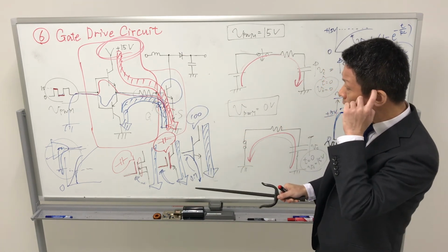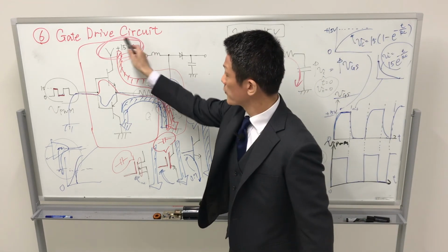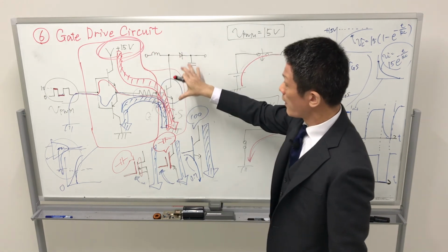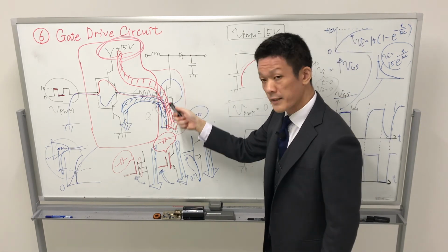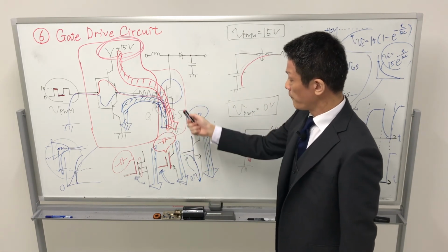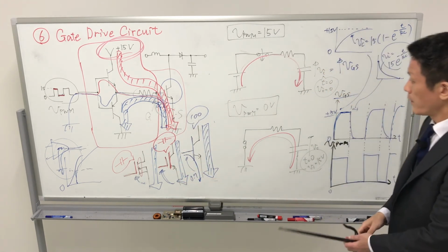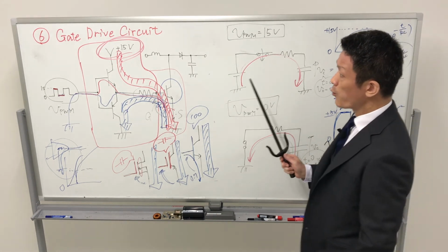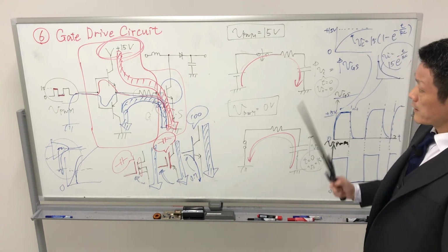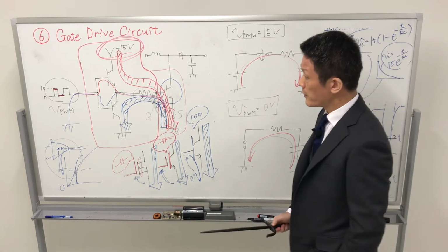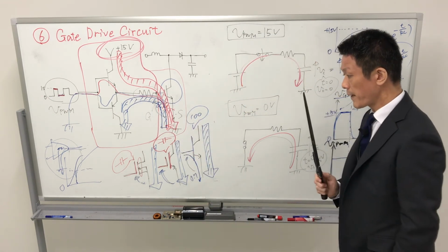So we must consider the current. So an additional power source line is required for the gate drive circuit, for operating the power semiconductor device, turn on and turn off, for charging the gate source voltage. That's why we require the gate drive circuit, okay? The gate drive circuit essence is the power line and current required. That is the important essence.